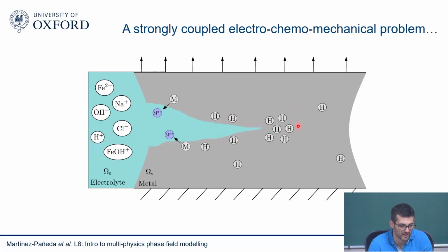So again, everything is strongly coupled. The corrosion process, the dissolution of metal, is also impacted by the mechanical fields. You may have a passivation layer here that you're rupturing through your mechanical fields. So there's many, many things happening, all of them strongly coupled, and this is the challenge. This is the problem with corrosion. Many things are happening across disciplines: electrical fields, mechanical fields, chemical fields.